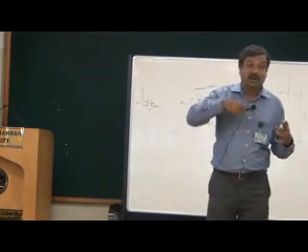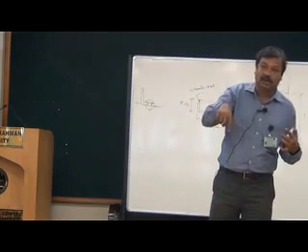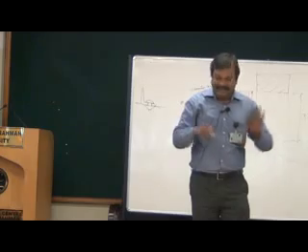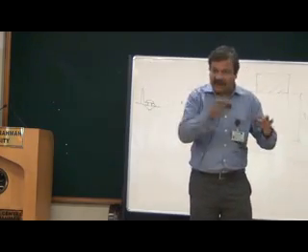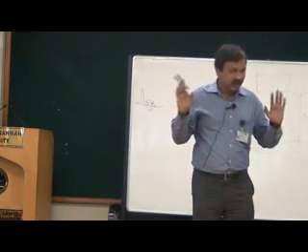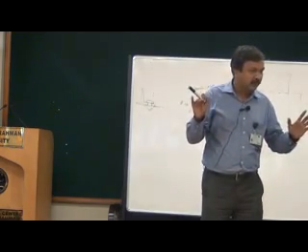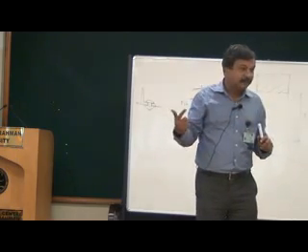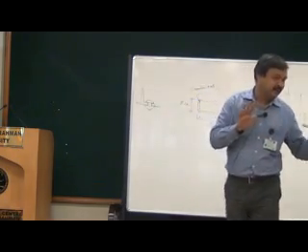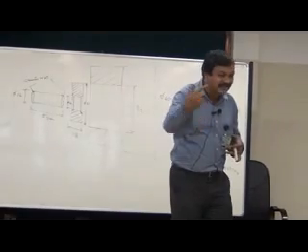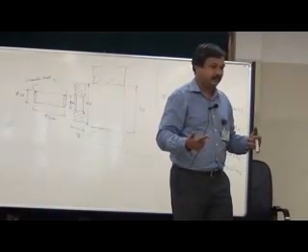On the other hand, a hole is an internal feature. Simple example: can you do turning on a shaft? Yes or no? Can you make an internal hole on the shaft? Drilling is fine. But more than that, can you do boring? Boring is much more difficult. Any process done internally is difficult.